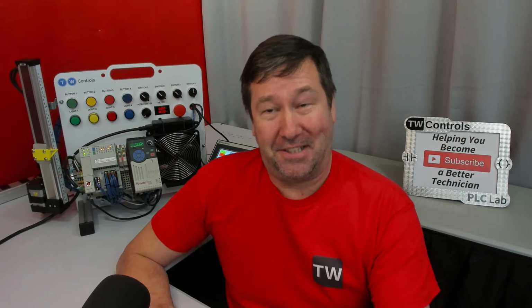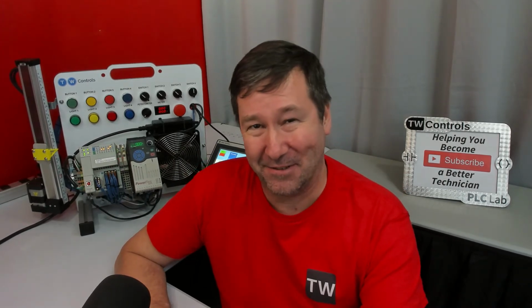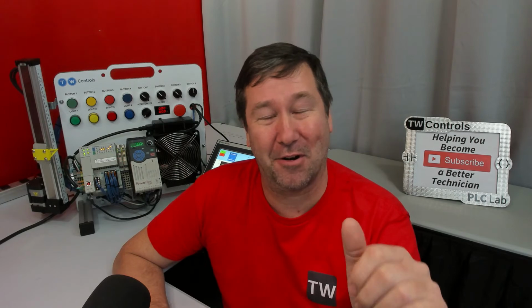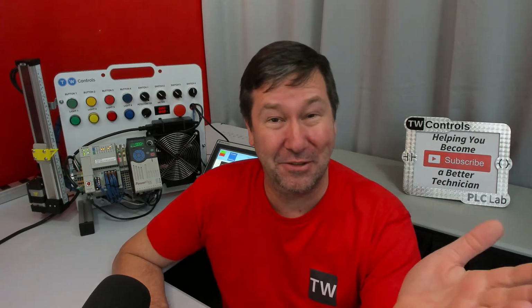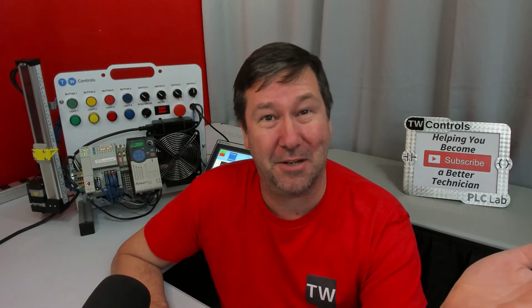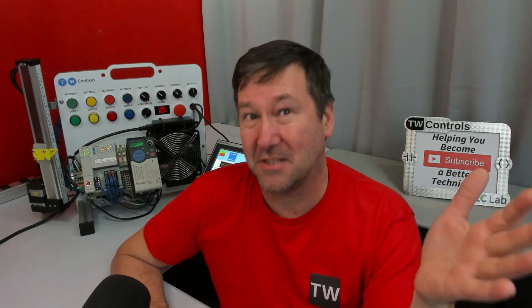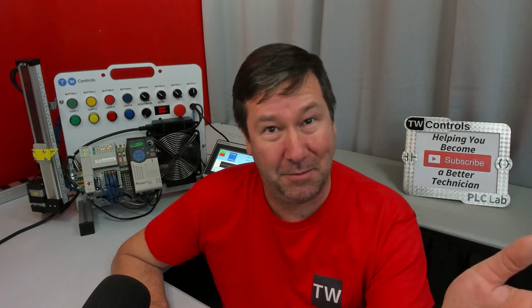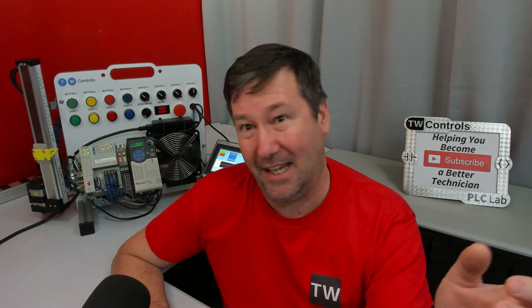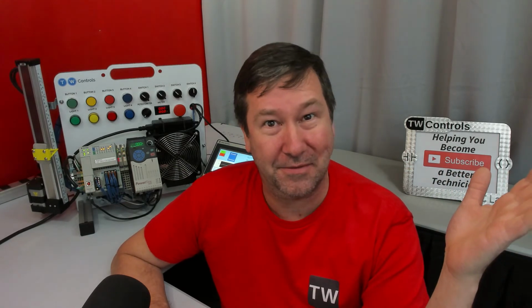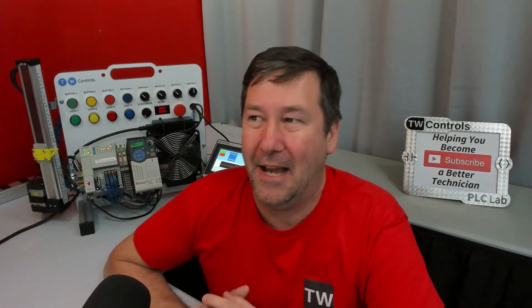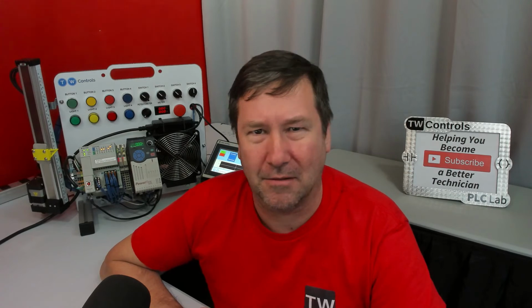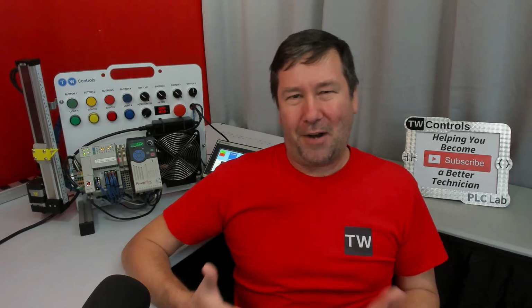Stop scrolling, because we have gotten into just one heck of a discussion over online edits. Really, this started a couple weeks ago. I was just going to do a quick live stream to talk mainly about how an always false instruction does not disable a rung, it makes it false. That led into a whole spiel of, well, hey, how does the program scan actually work? Because we saw the light flickering. And finally, someone asked me, hey, well, how would we edit a rung? How did we end up here?